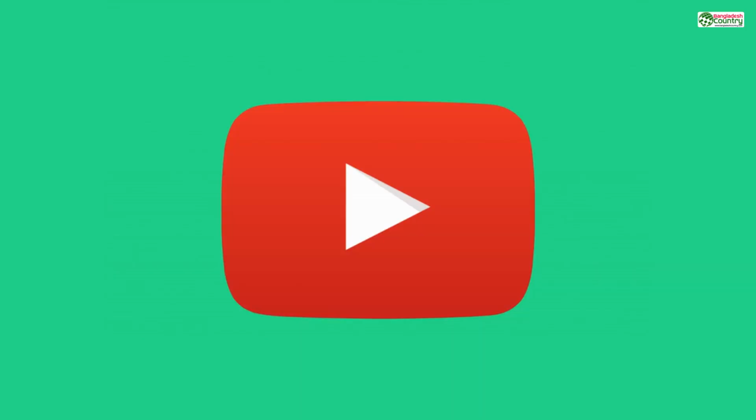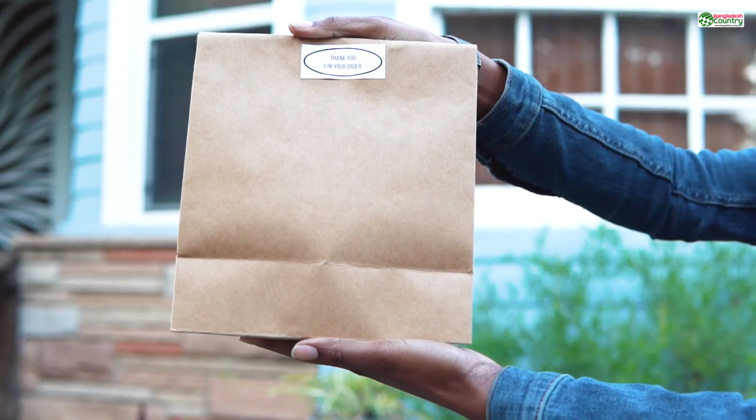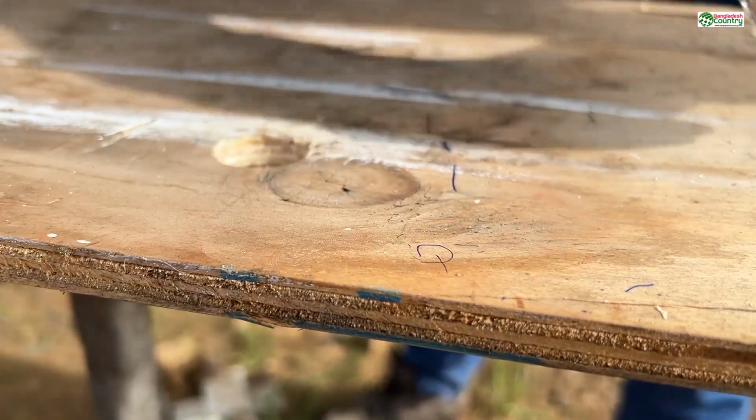It has a button that says Thickness. You type in the minimum thickness from your service's design guide, say 1.5 millimeters, and you hit the button. It will analyze your model and highlight every single area that's too thin, usually in bright red.